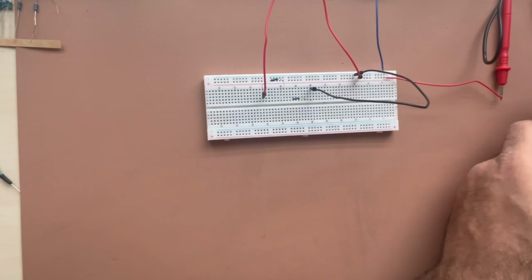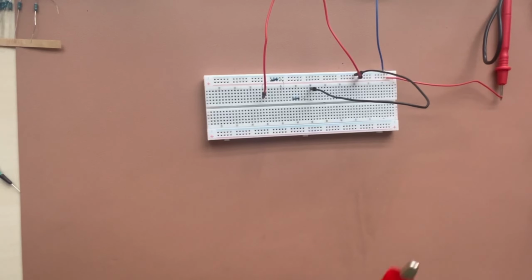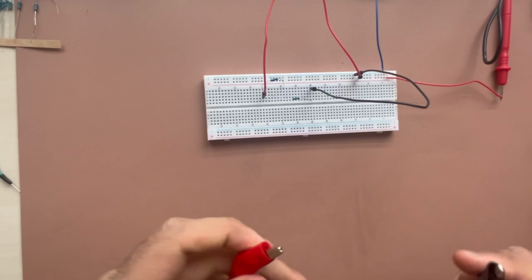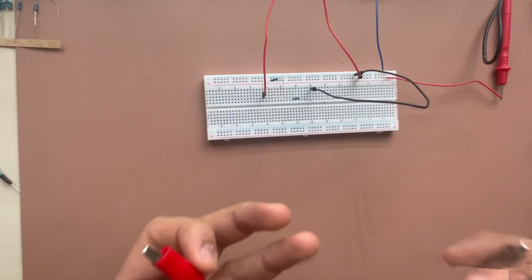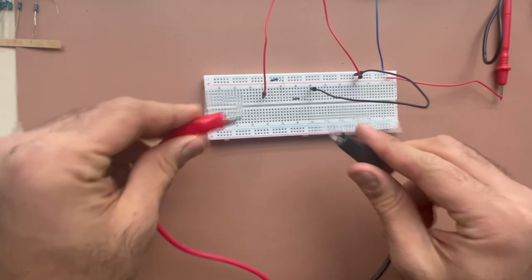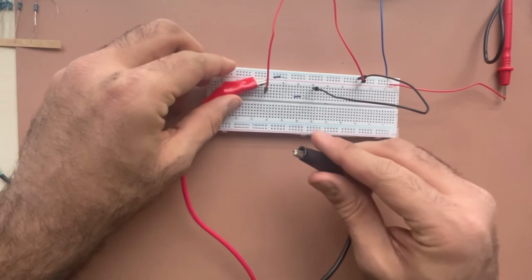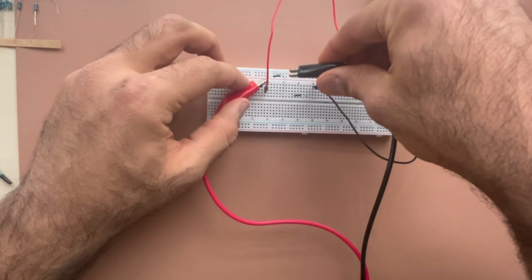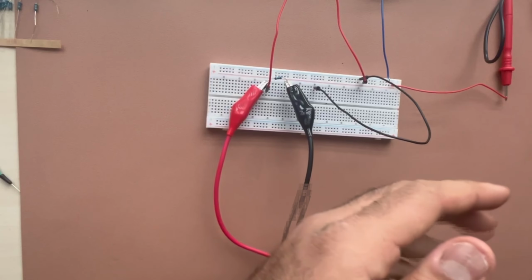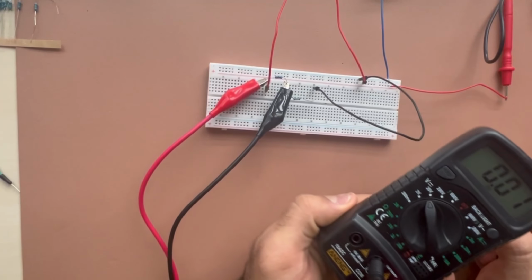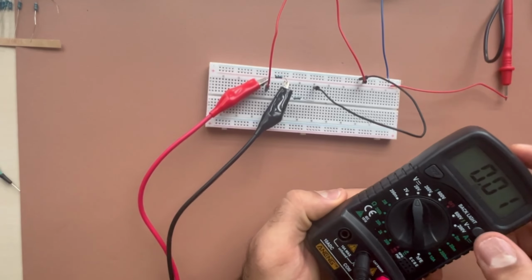So let's use the voltmeter in order to measure the voltage for the very first one. As we know, based on our calculation, the voltage of the first resistor, which is 1K, should be 5 volts. So I'm going to connect this one to the positive section and this one to the negative section. The only thing that I have to see right now is that as soon as I start up my voltage source, I should have the 5 volts or not.